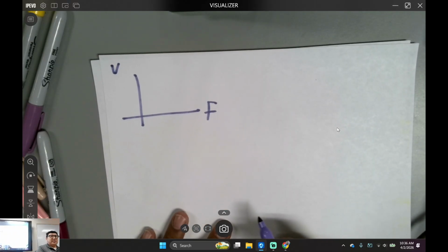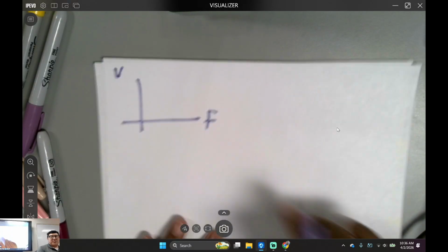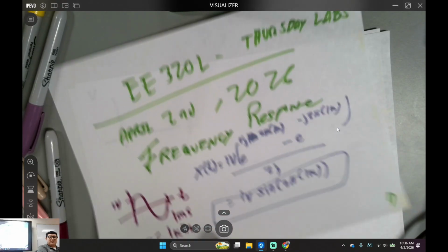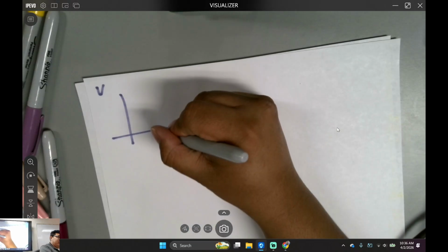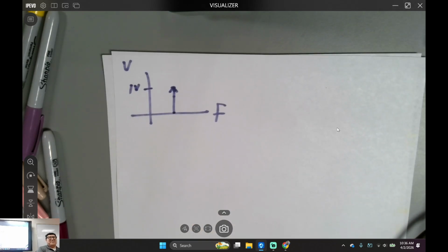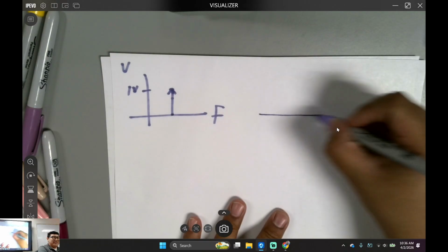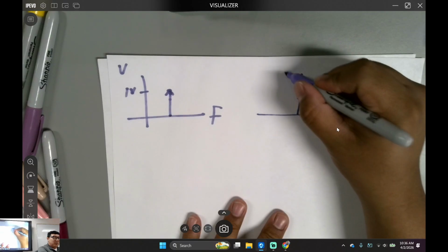Does that make sense? What am I going to see in terms of frequencies for just that one sine wave that we had right here? What are we going to see? This would be a one-sided Fourier transform. If I wanted to do a double-sided Fourier transform, it would be like this. This is 1 volt.